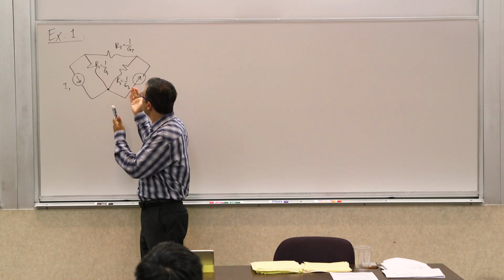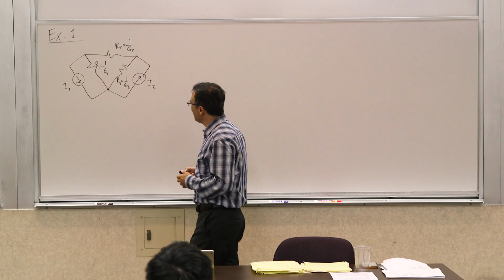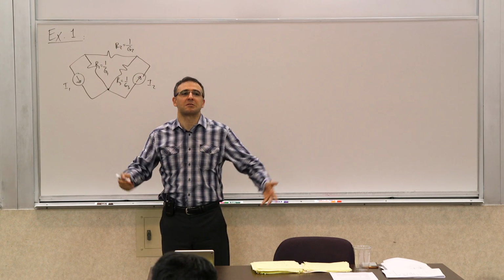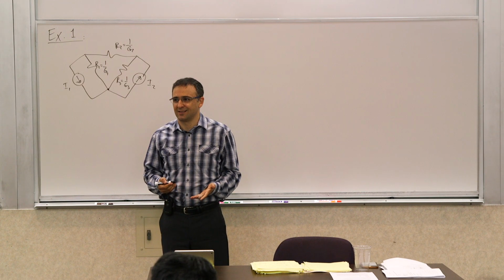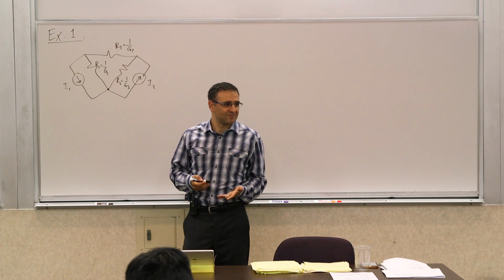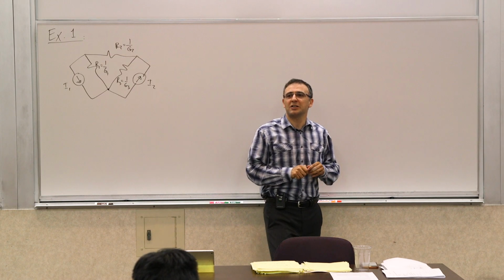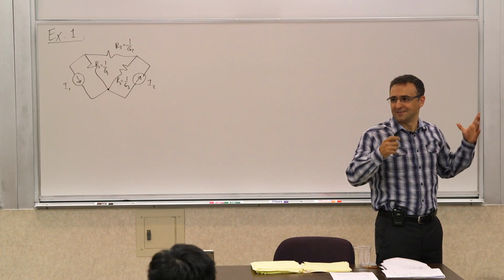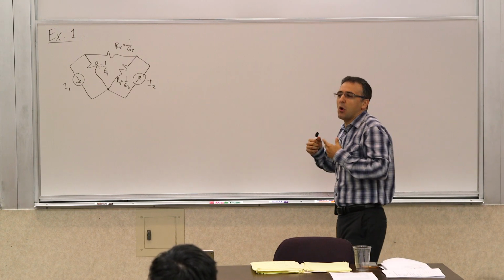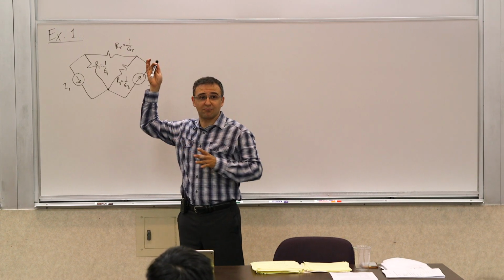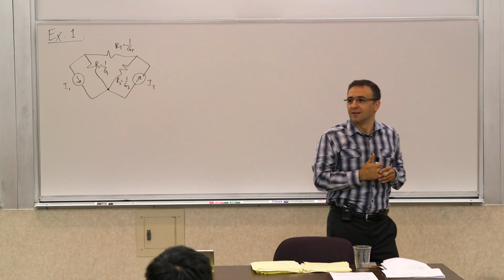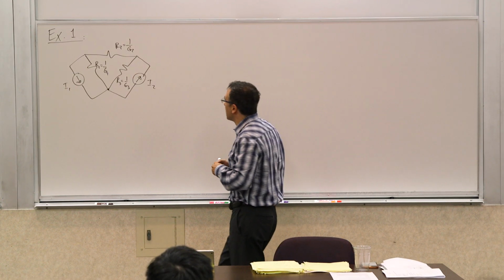So anyway, if you're solving a problem, I generally recommend picking the node that has the most things attached to it, because you will get rid of the node with the longest KCL. You want to keep things as simple as possible. So again, this is not part of the algorithm. This is a rule of thumb, right? But it's basically something of that nature.